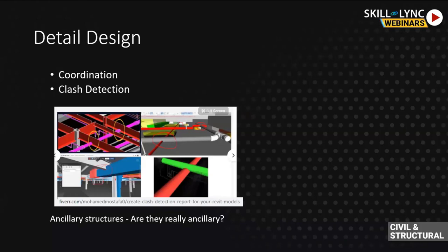The geotech report, have you studied it properly? Do you know the capacity of soil where you are working? It's just not the numbers. It's also about how well you are asking the questions that are very necessary to be asked. Sometimes you don't have the data. Do dig for data. Do not assume things when you don't have the data. Assuming things can again cause a lot of money and problems.